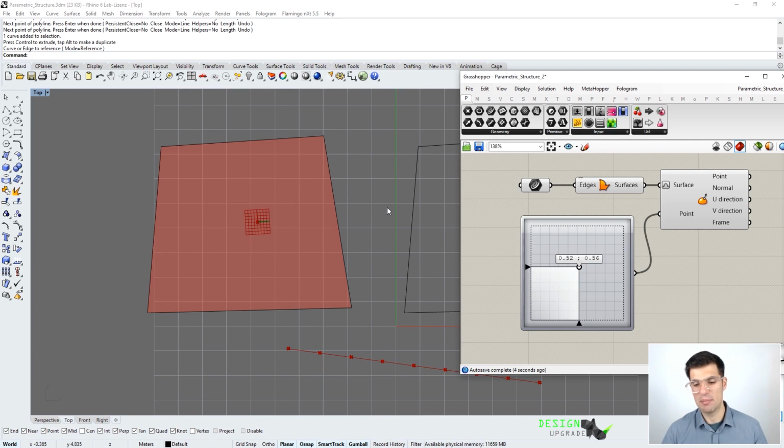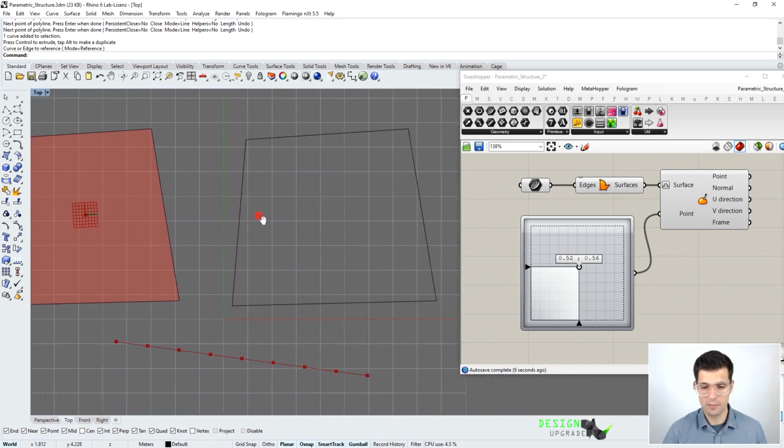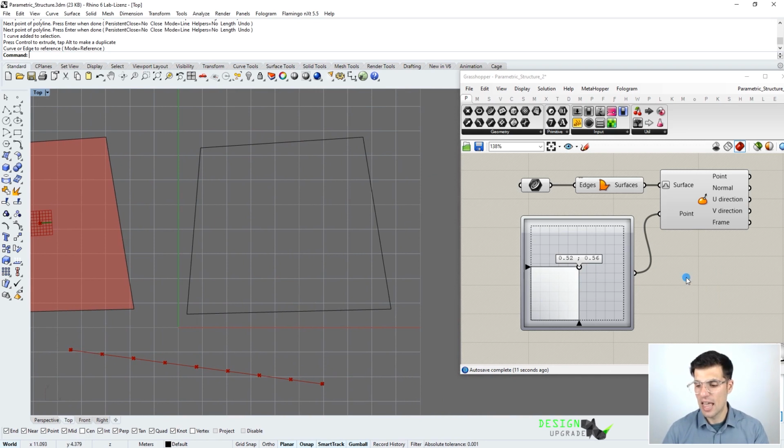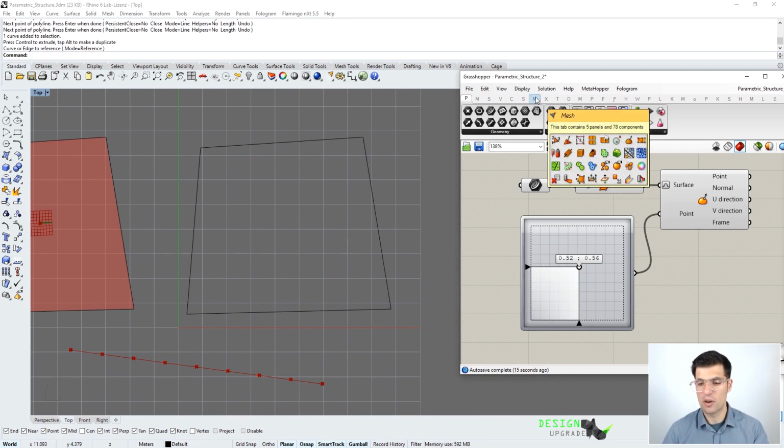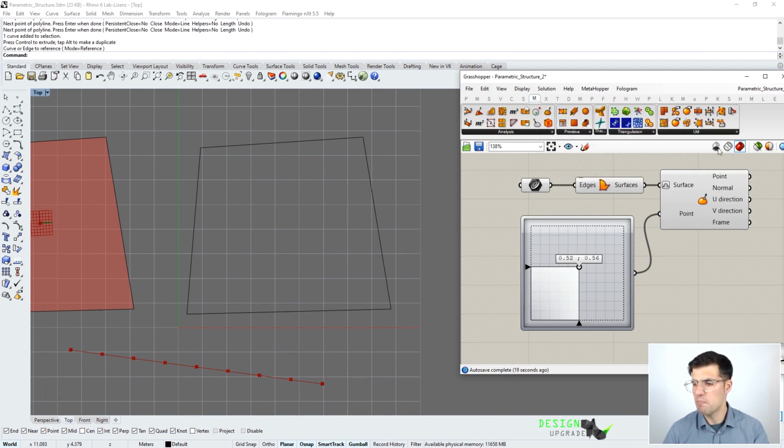But as I said before, we have another possibility to define, let's say, surface geometries, which is using meshes actually. So in order to explore what meshes are, you can come to this mesh tab here, and you have a lot of possibilities here. So of course, if you have used the finite element method before, you already know what a mesh is, but let's define one in Grasshopper.